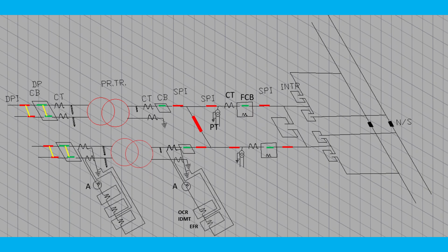For the HV side, that means the incoming side, we are using an ammeter, then one overcurrent relay IDMT to permit the overload. Our traction transformer can bear 200% overload. That means if it is 10 MVA, it can deliver 20 MVA, but only for 5 minutes.